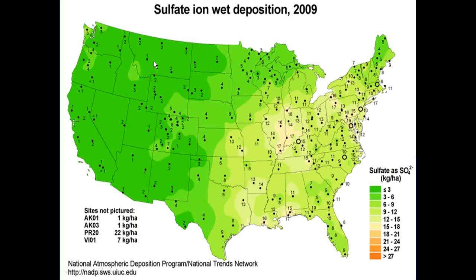So as you look at each one of these maps, you will see there's not a single place in the entire United States we don't encounter chlorides, sulfates, and nitrates. So it isn't a matter of you only have to test if you're near a marine shore. You don't have to only test if you're in what they call the Rust Belt. You're going to have contaminants nationwide every place you go.